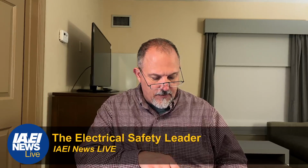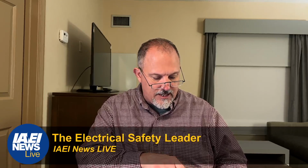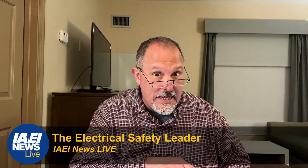General, except as otherwise provided. You have listed units. You have gas-fired water heaters. So, except as otherwise provided in this section, the outlets that supply a self-contained spa or hot tub, a packaged spa or hot tub equipment assembly, or a field-assembled spa or hot tub shall have GFCI protection complying with 680.5(B) or SP GFCI special purpose protection complying with 680.5(C) as applicable.